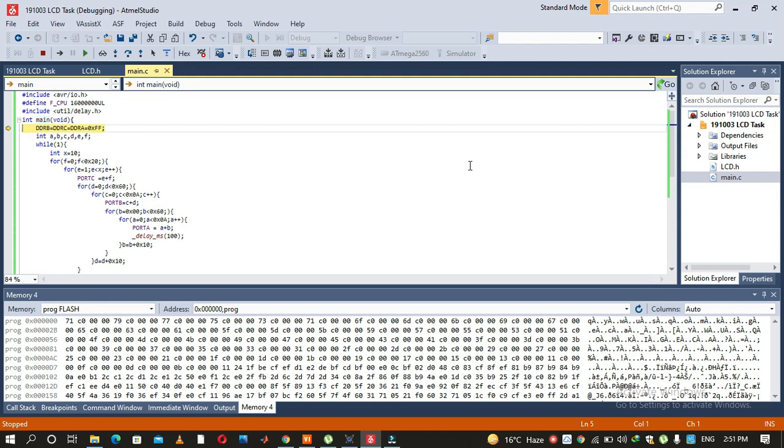So the next code in Lab 4 that I am going to explain is the same as before, using BCD LEDs and 7 segment displays. We have to display a clock having 2 digits for hours, 2 digits for minutes, and 2 digits for seconds. To do that, I have used 3 ports of my Arduino, which are DDRB, DDRC, and DDRA, and declared them as output.